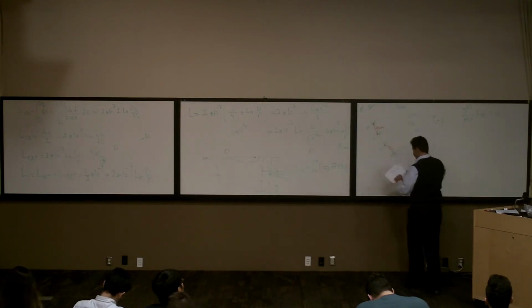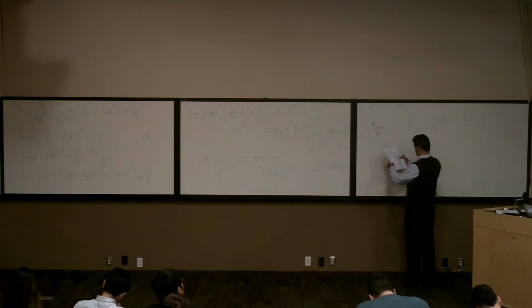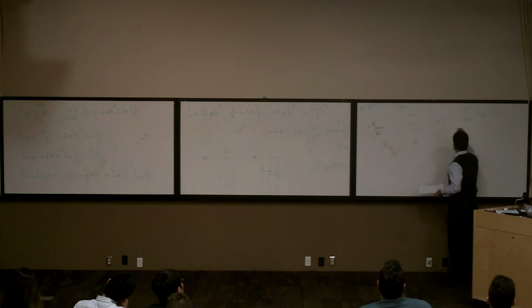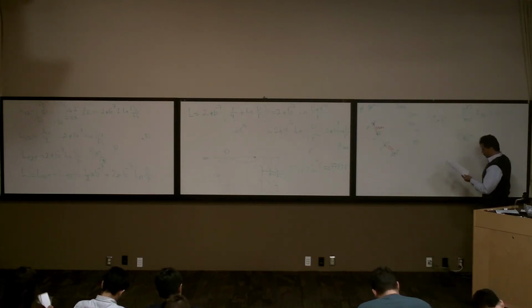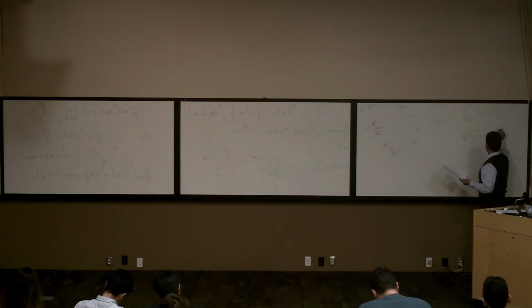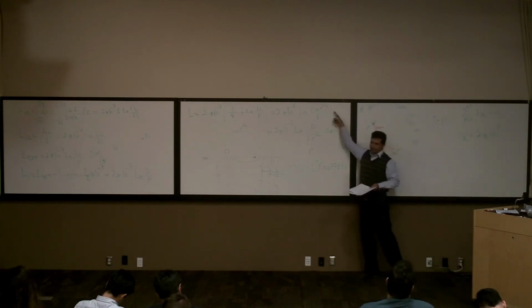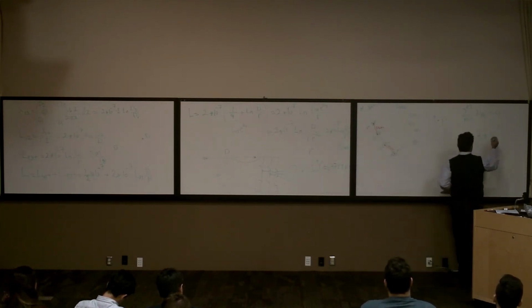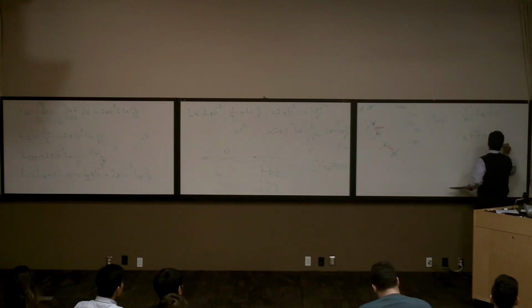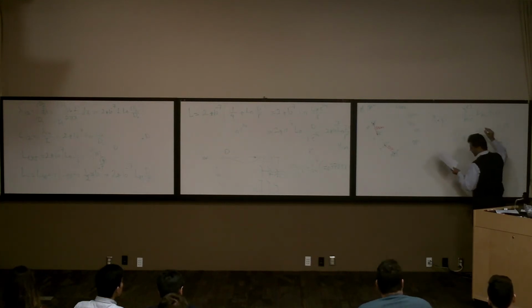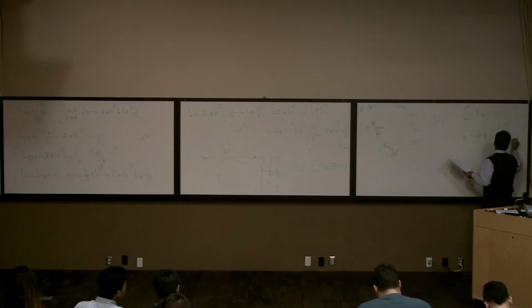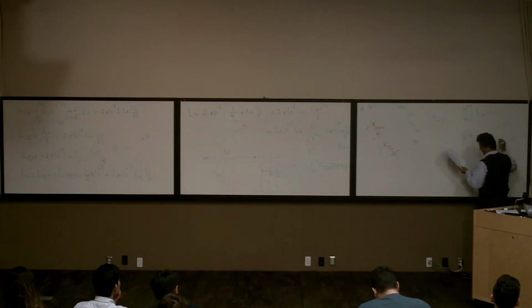We call it lambda k. So lambda k is going to be 2 times 10 to the power of minus 7, same thing as here, times the sum from n equal to 1 to N of I_n times ln of 1 over dkn.